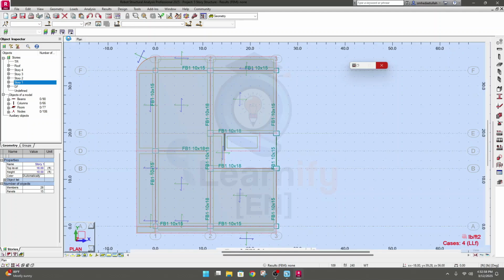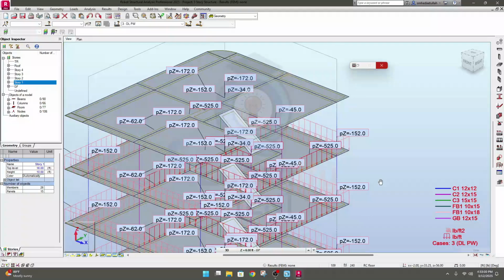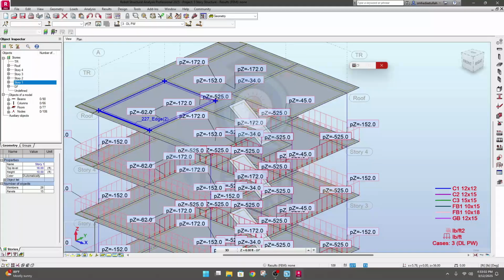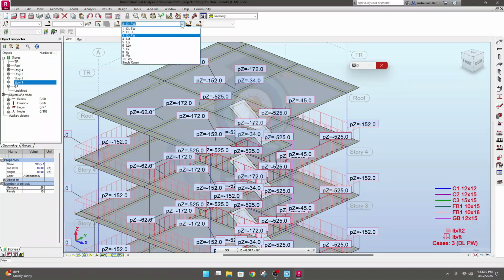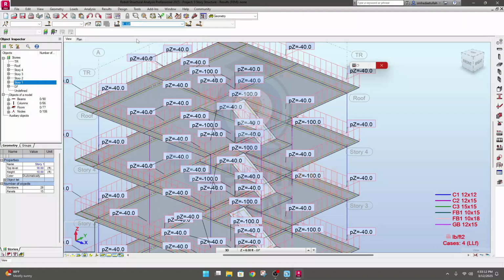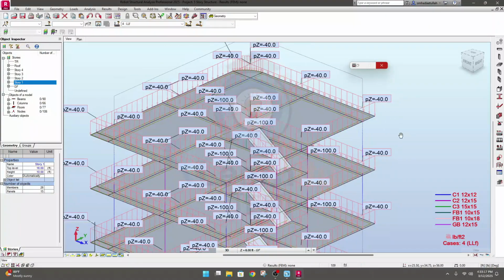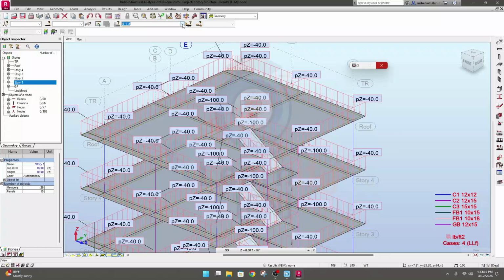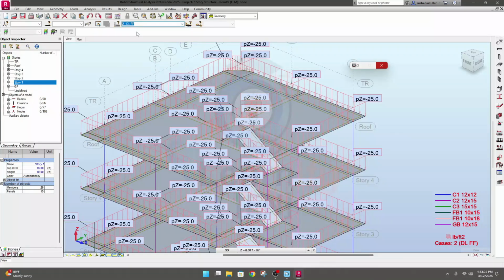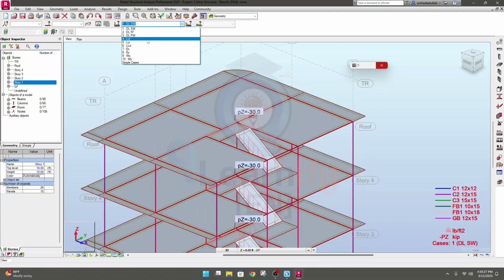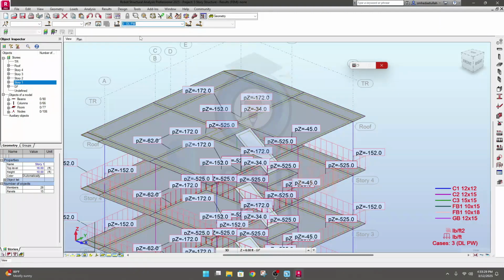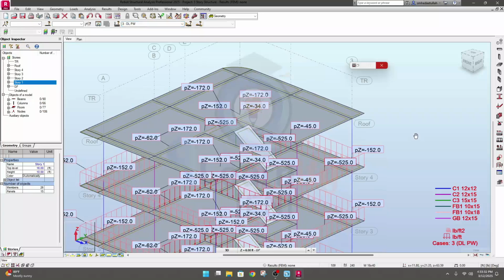And if I go view, so here you can see, sorry, this is partitional load, live load floor. So in live load floor, we can see this load is available here also. So what we'll do, I will delete it again. So floor finish will be available. Self weight will also be available. Then our dead load partition wall will not be available here.